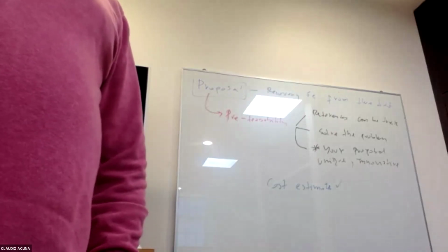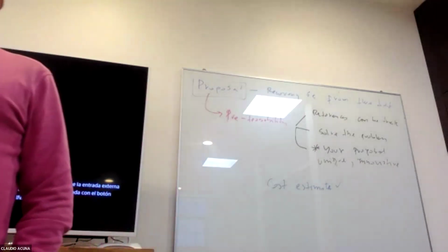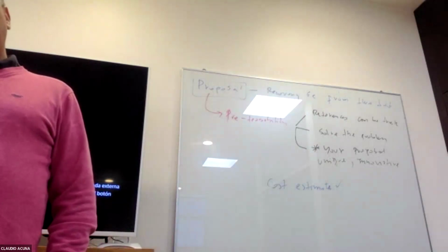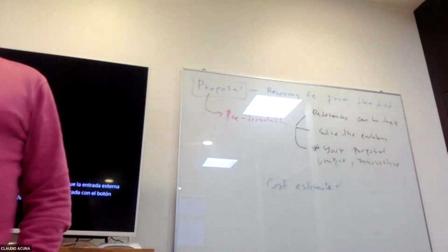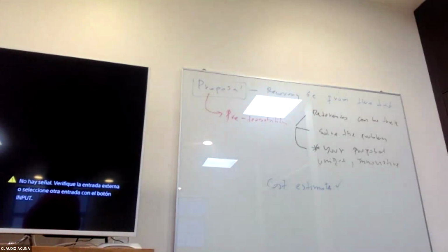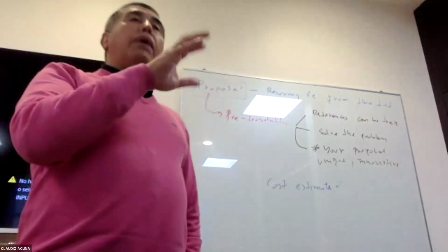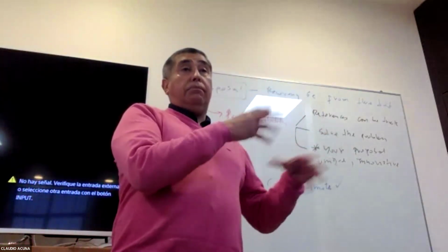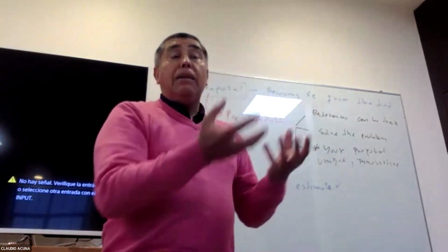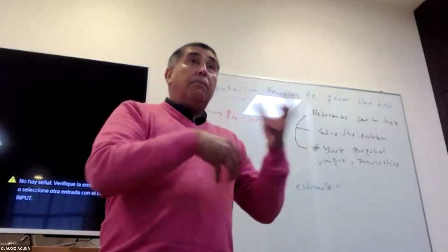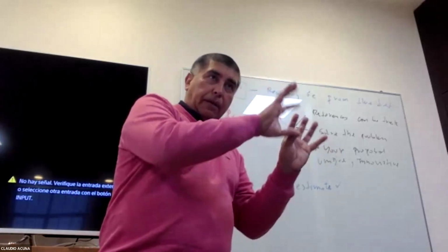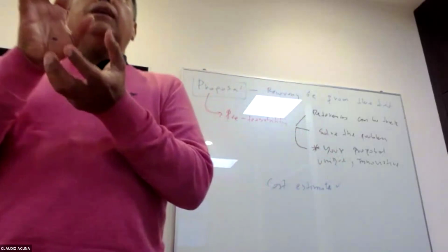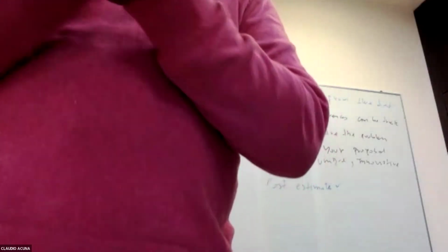We'll come back to that when I show you a general process when we work with the tailings. We just finished a project with MATLAB to have multiple flow sheets and evaluation. You will see. Okay? This is a block diagram. You have a general one. To answer you, you will have repulping or producing the pulp. Mechanical liberation, if it's the case, repulping, this is one specific stage. And then we call it chemical liberation, which is leaching. It can be autoclave, atmospheric, alkaline, but you remove from the matrix solid and ion.